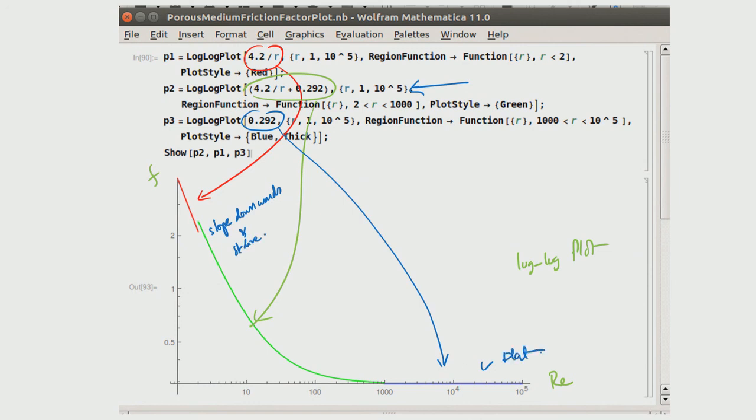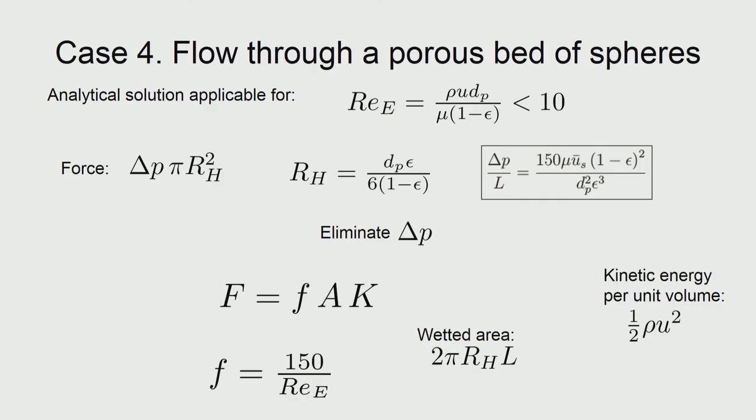So, when we do not know any expression for these things, then we define the friction factor the way we have seen earlier. When we write it like this, the behavior is already known: a straight line on the left hand side and flat on the right hand side. The expression for a porous medium made of a bed of spheres is identical to the porous medium we have seen earlier, except that S naught is taken as 6 by dP.